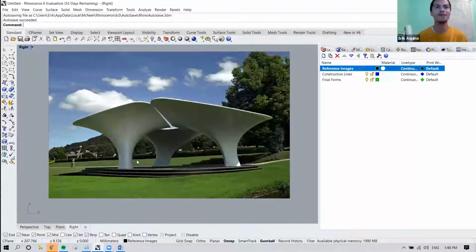How I would make a form like this is I would take the cross-sectional profiles throughout the z-axis, and we'll use this command called loft, which will merge these profiles together. As you can see at the bottom, we don't really know what that profile is. Could be a circle, could be like an adjusted rectangle.